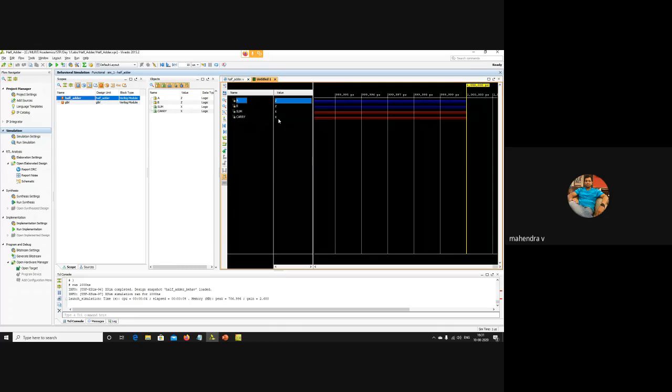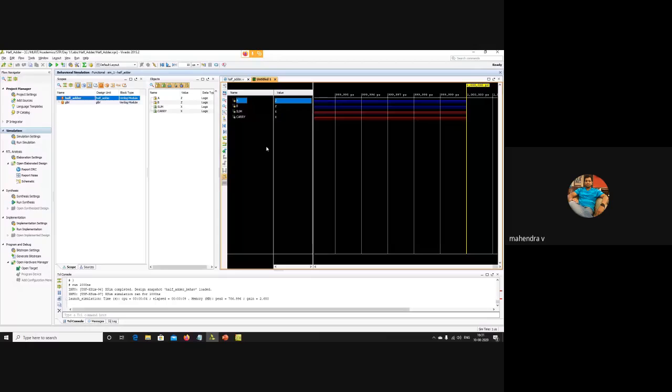So now I am getting the window. If your license is not done for the software, then you will not get this window. That license is the triggering point for the simulation, synthesis, all these things. For writing the HDL program, no problem. But for simulating the HDL program, we need the license. Now I will tell you today how to give the inputs manually. Tomorrow I will explain how to write test benches, because we are already running out of time. Tomorrow I will tell you how to write test benches for automatic inputs.